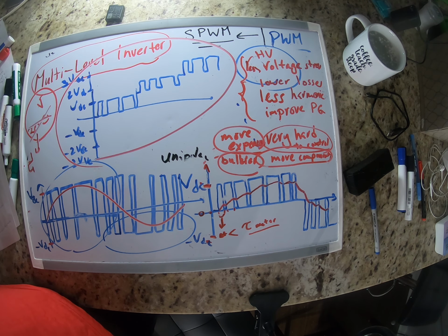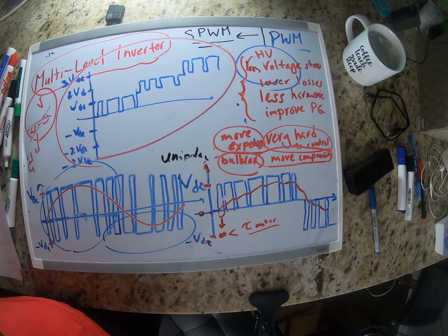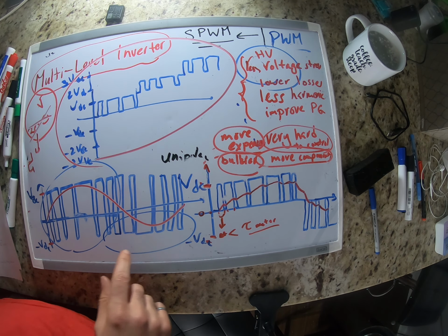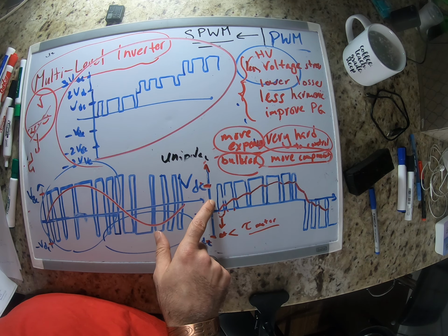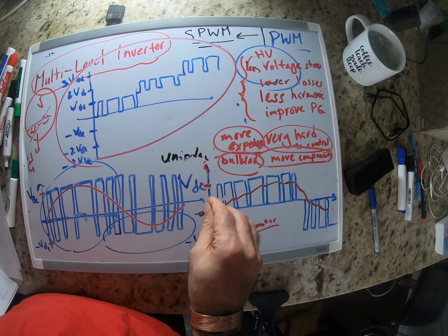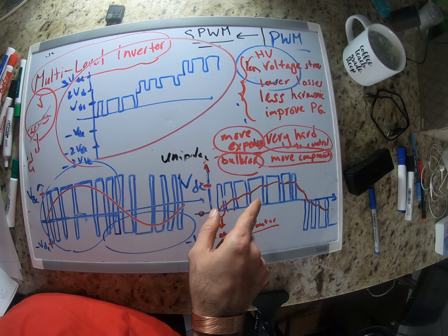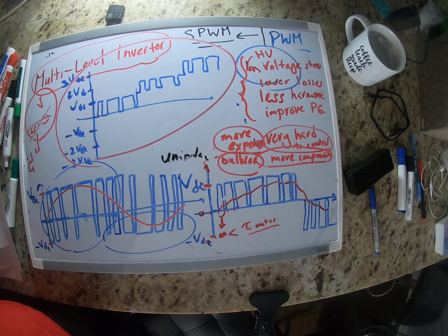So that's why multi-level inverters are used in the industry when you need higher voltage, also when you need higher efficiency. Many standards might not be achievable with a two-level inverter. If you want to make your THD smaller than a certain value, it might not be achievable with two-level, but it's achievable with three-level. So that's some practical points here. I'm just going to see if I missed any point for this lecture. It seems that I covered everything.